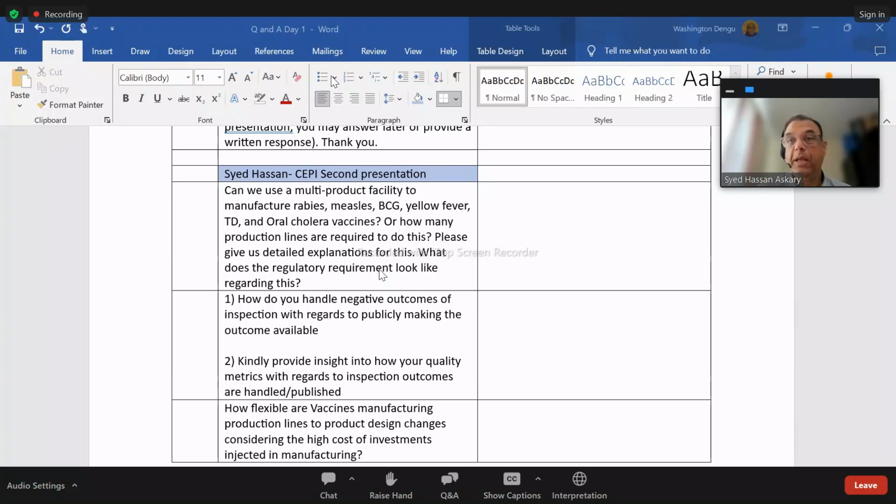Are you gonna use the same process flows for all? The fourth thing is, in an overarching response, I can say yes, because now more and more companies are looking into doing that. They're building facilities, but when you deep dive, there are more layers to it. I would recommend that before even starting to develop the facility, you go and discuss your design and strategy first with your national regulatory authorities, and identify how you're going to do containment control, which is critical in this case, especially BCG.